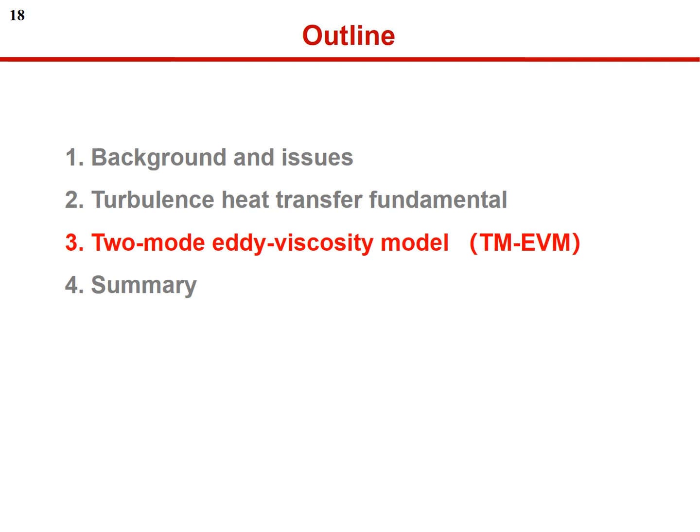In the last session, we have discussed the peculiar properties of supercritical fluid turbulence. Now, we will focus on turbulent eddy-viscosity modeling theory. Based on the physical mechanics of supercritical fluid turbulence, we first established the statistical equation, and then we obtained the modeling of physical parameters, including turbulent kinetic energy, turbulent dissipation rate, and eddy viscosity. Finally, the modified model is obtained.